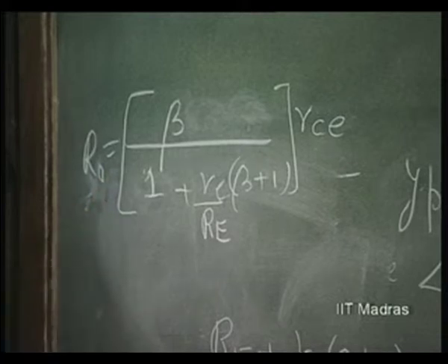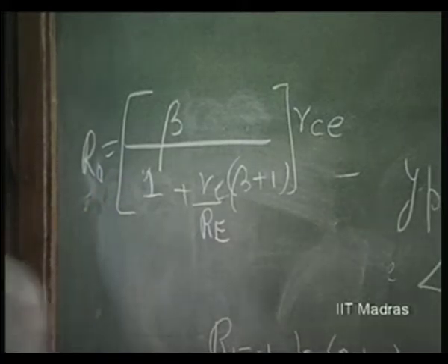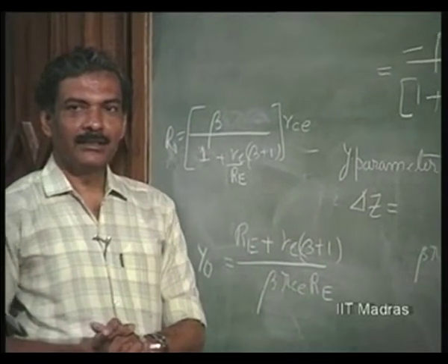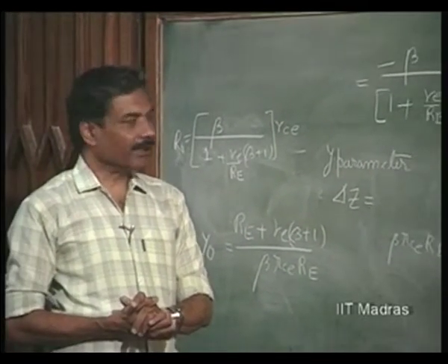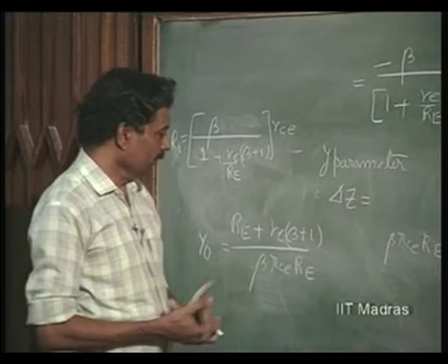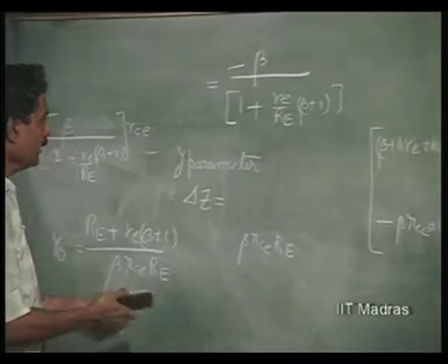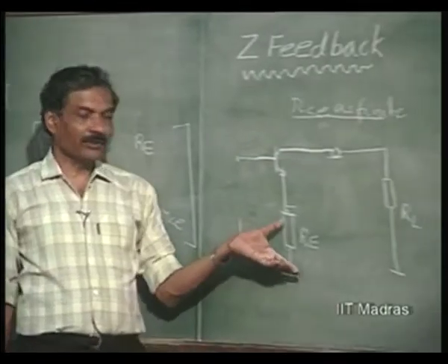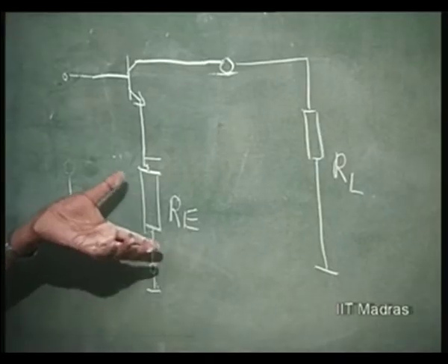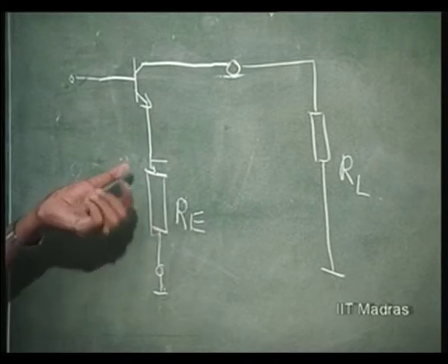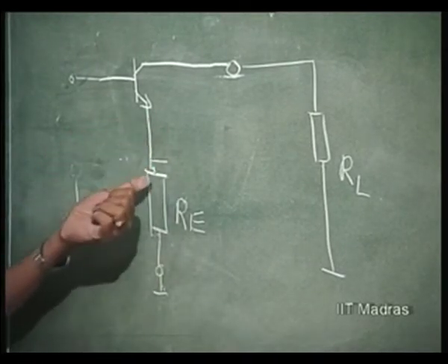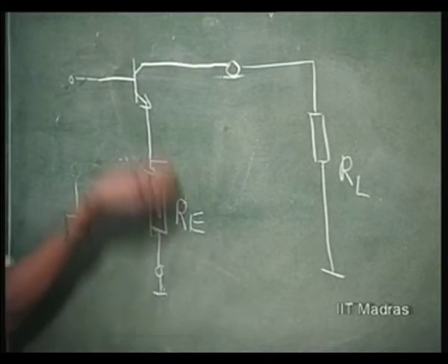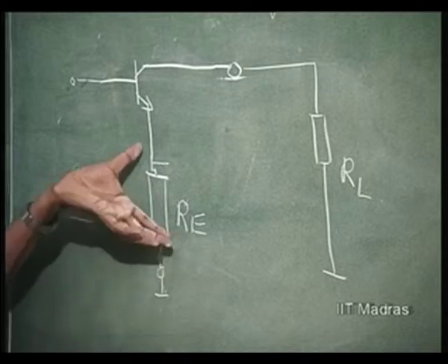So, you can see that almost every way it is going towards voltage controlled current source idealization. So, this is a very simple negative feedback circuit. This also can be thought of as a situation where emitter bypass capacitor has been removed and consequently it gives feedback.